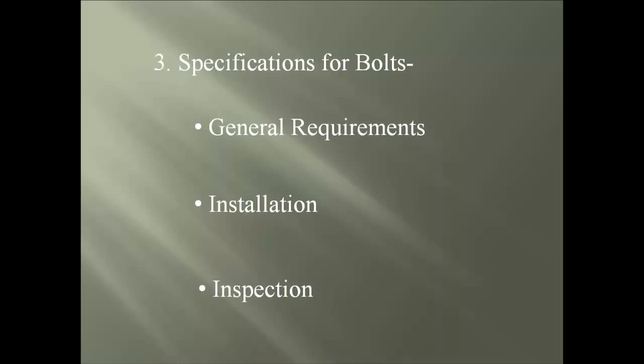And the last item of this segment is the inspection, which, when required by contract documents, ensures the work in progress meets this specification. The following joints are covered: snug tighten, which must be visually ensured that all plies in the assembly have been brought into firm contact.